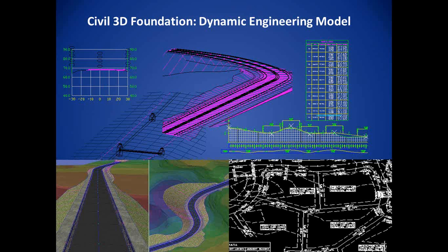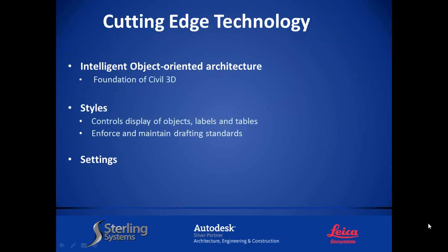Everything should be good. Is all of your design labels, if you rotate the drawing 90 degrees, they automatically update and orient themselves correctly. If we change the drawing scale on a site design from 1 to 50, 1 to 100, they automatically scale all the labels as well. That's another reason in the newer versions of just AutoCAD, you have annotative scaling. Once you get the hang of it, everything automatically updates as well. And in Civil 3D, every single style is built into that as well.